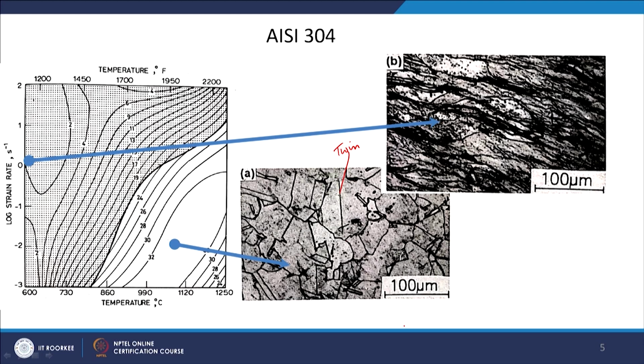And of course, the microstructure is again recrystallized. So, there is no issue with this microstructure. In this processing condition, I should get this kind of microstructure, whereas in the unstable region, where it is at higher strain rate and lower temperatures, you can see a lot of flow localization has taken place, all these dark regions.